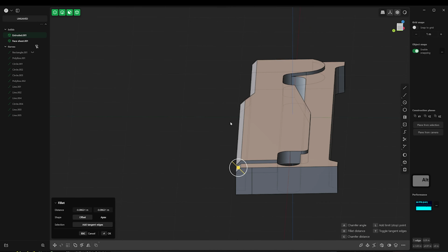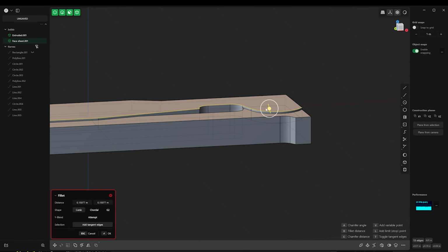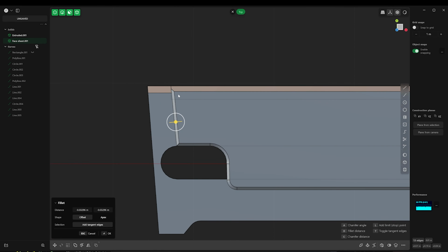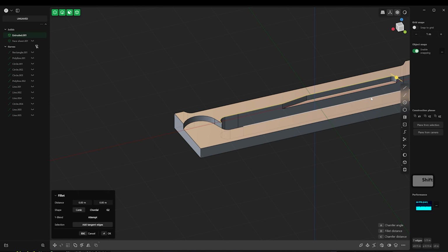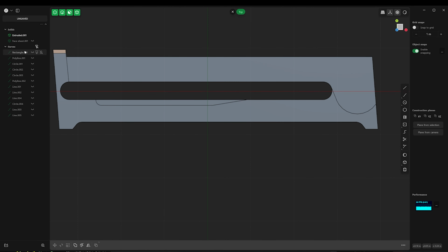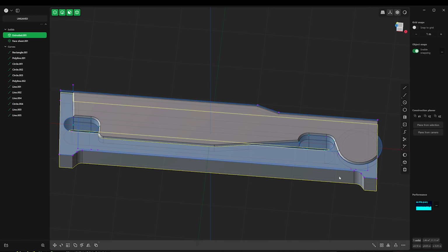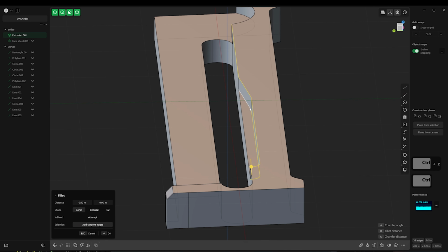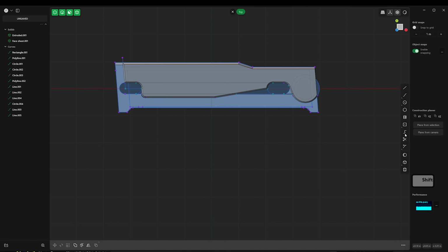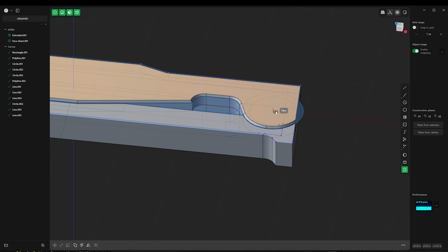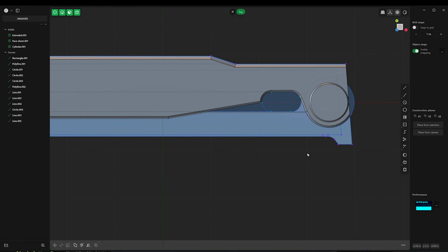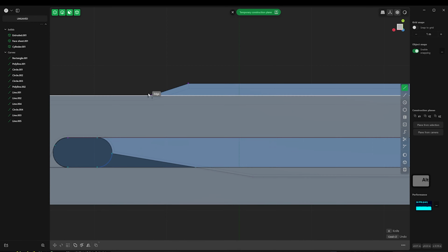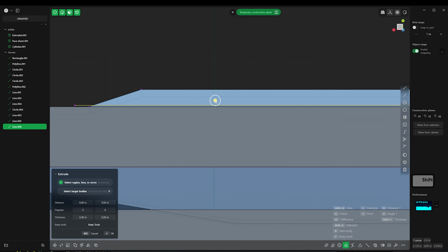So in this part, you've seen the workflow that I started with. I basically laid down a bunch of curves, because that allowed me to adjust the proportions and try to get all the proportions in order. I then used the extrude tool to generate my first shape, and then using that, some more of the curves I generated on the top piece, which slides out of the way. It's basically like the locking mechanism of the knife. And then I'm just laying down the bevels.